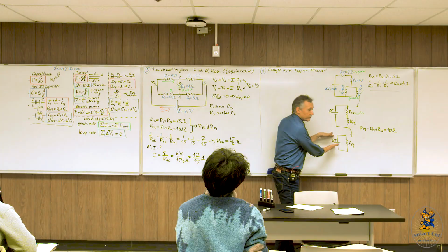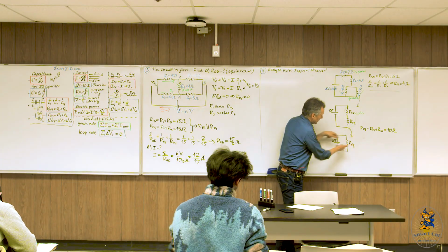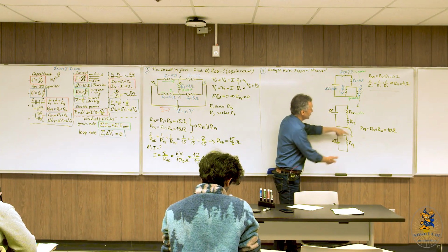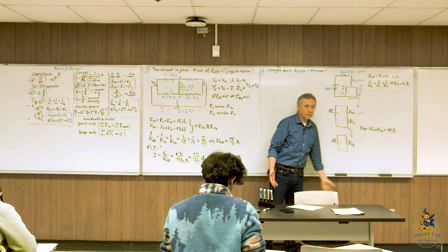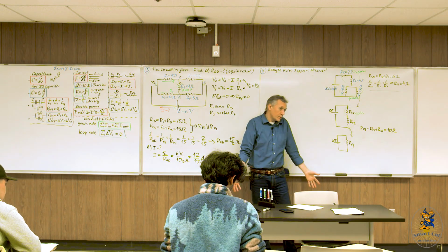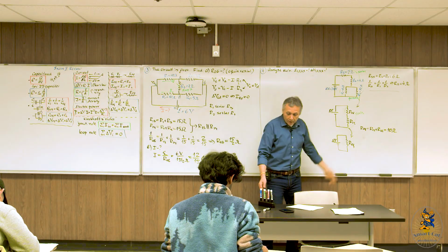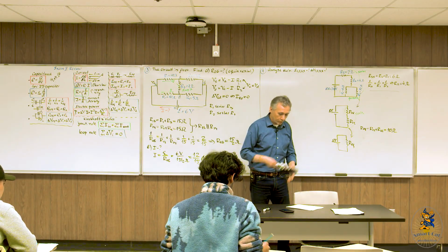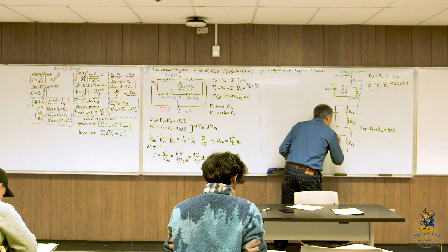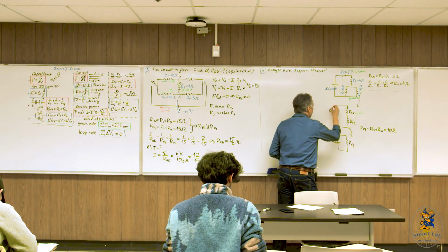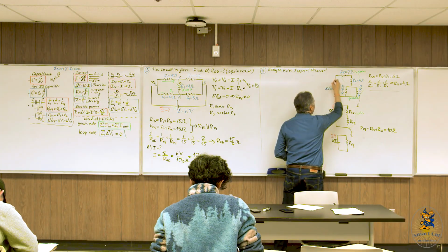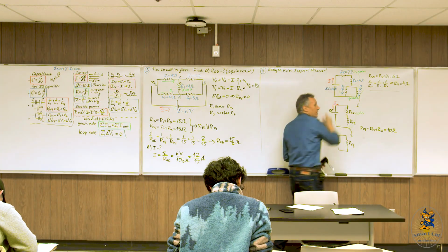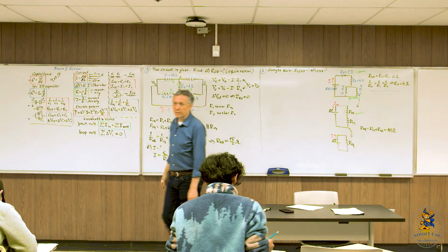So we have the potential difference across this resistor, which is 24 volts across a 10 ohm resistor. So what can be found? Of course, current. Of course, a trivial question. So now we can find the total current taken from the battery. So essentially, we're finding this current I total, which is over here and over here. It's the same current, because that's how this method was developed.